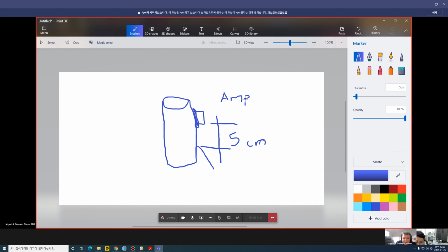And you have the wax, okay? Then you are going to perform the pencil lead break five centimeters away, and you are going to measure the amplitude. What I am telling you is, if you use a piece of tape around your sensor and the test piece to apply pressure to the sensor against the surface, and do another pencil lead break and measure that amplitude, to see if with the tape around it the sensitivity is improved.